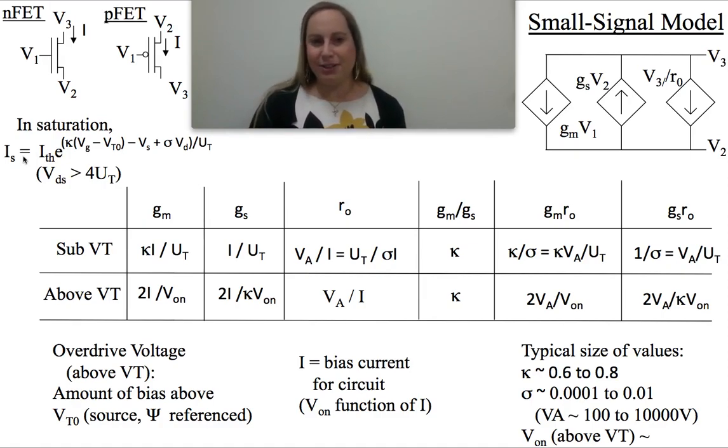Now the nice thing about exponentials is the derivative of an exponential is really just an exponential, and then other things come out of it. So it's a very useful and nice formulation for many of these systems. Also remember, if you've looked at a couple of circuits already doing large signal and subthreshold, we already know that the solutions are basically linear. So not a bad thing to do small signal modeling, but don't forget that you really can do some large signal solutions. Above threshold sometimes is the only way to get a reasonable solution in a reasonable amount of time. But what's interesting is if I take this definition of source current, it's got three components.